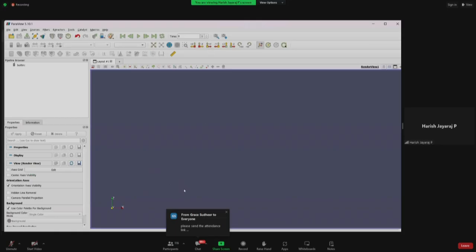So that will make your geometry in the Y normal plane, which is the XZ plane. The geometry is made in the XZ plane, but by default, ParaView loads in Z normal. So you have to change it by pressing this button. Then you can see the surface. Then after that, you change the surface to surface with edges to view it.